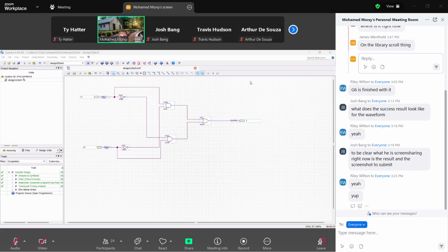Then we highlight X1 and we click on a symbol like a clock, which is overwrite clock. Click on this and we choose 4 microseconds for the first input. Okay. Then highlight X2, do the same thing, choose 2 microseconds. Click OK. So we have the inputs now.